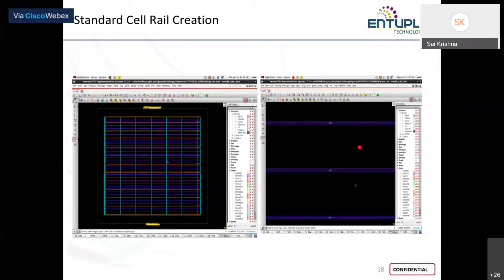I repeat, the EDA tool might place any standard cell partially or fully outside the core boundary, which results in not fabricating that part outside the boundary, and hence collapsing of the functionality. So exactly at the left and right boundary of your core, we place two dummy cells which act like blockers. That means they do not allow any standard cell to be placed outside your boundaries.